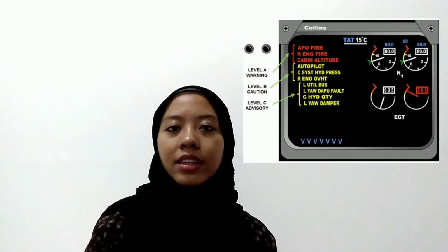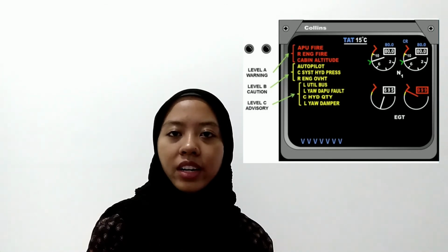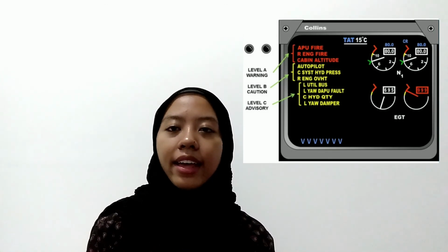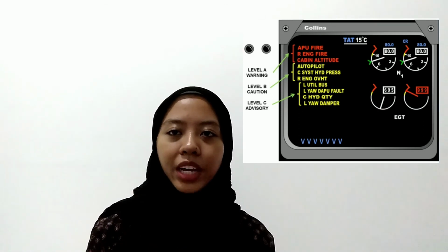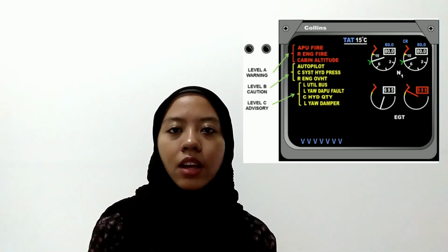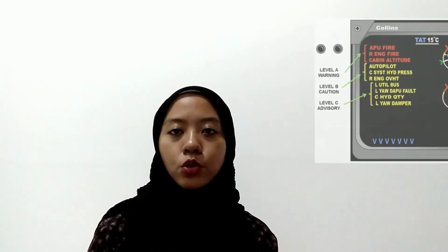This system provides alerting messages to the crew that are posted on the display in the form of warning, caution, advisory, and system messages. It will light up the switch lights on the specific system control panels to provide component or system status or to prompt corrective crew action.